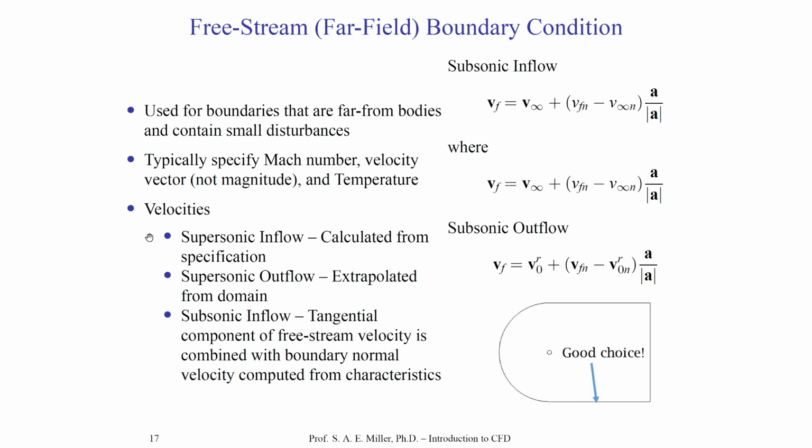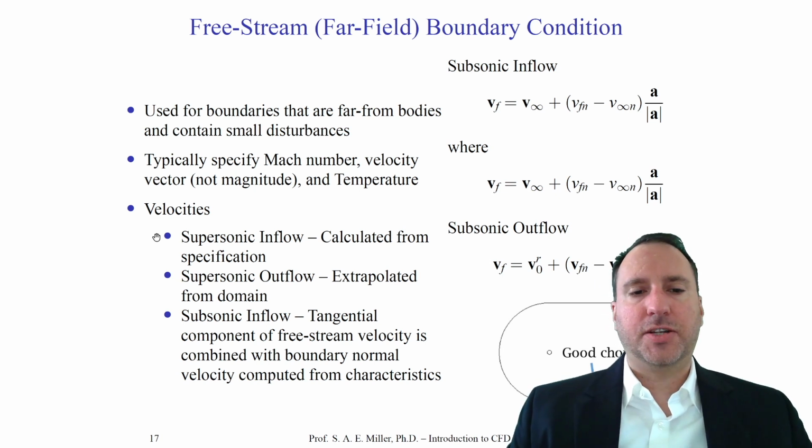For every time the solver makes a time step or iteration and solution, which we'll talk about later in the numerics section, we must detect if the current flow is into the domain or out of the domain. If it's a supersonic flow into the domain, we simply calculate it from the specification. If it's an outflow, we extrapolate it.